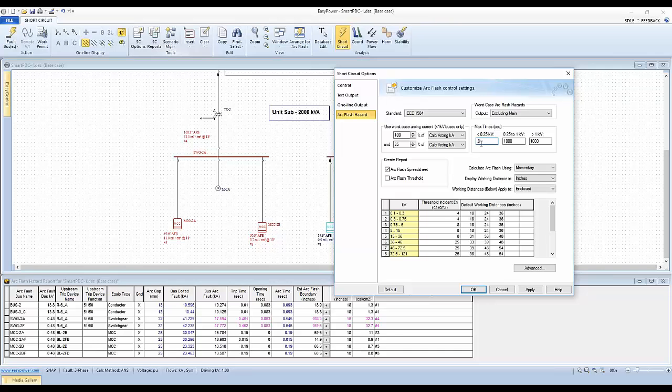So this tool allows us to set the maximum time for those types of faults based upon entering a number here, and depending upon your system and the type of equipment you're using, you may be guard banding by as much as 300% by putting in 1 second as far as a maximum time, or you might even put in less than that if the current's low, because even at 0.6 we have 100%, you see 100% guard band as far as that particular safety factor on a bus that's less than 250 volts.